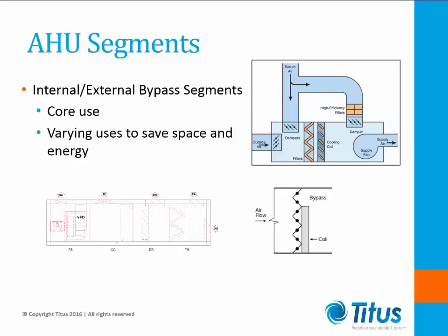Things to consider when sizing the cooling coil and bypass: attention should be paid to the cooling coil to make sure it will provide the required latent cooling at less than 100% airflow of the unit, to allow adequate bypass air to mix up with the minimum supply air temperatures. Face dampers for cooling coils are not always required. The airflow through the coil will be considerably higher than through the bypass section.